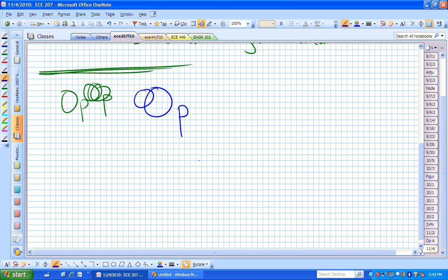Let's now try to solve this particular circuit. Any other questions? Question? Pardon? So, yes, in this class, we will always have our currents going into the operational amplifiers. We are going to neglect those. They're effectively going to be 0 for us. So I1 is going to get to that node, and none of it's going to go to the right as I sub X. It's all going to go to I sub 2. That's basically what that's telling us.